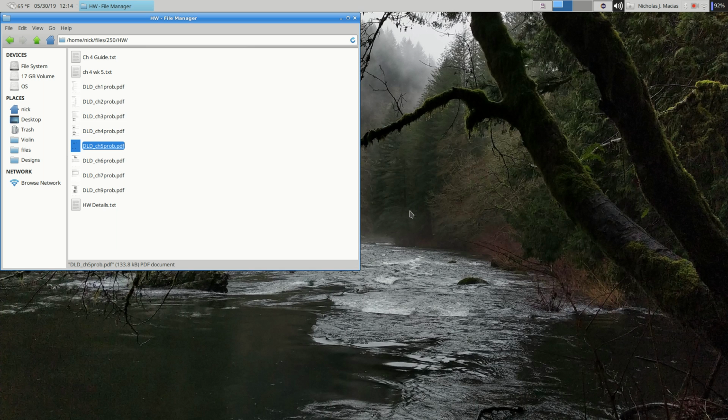And on the homework, if you're moving from state to state correctly and you're not explicitly generating outputs, that's not a big deal for me. So the trickiest part is coming up with the machinery for the flip-flops and how to update the state of the system. And the output's usually just another piece of random logic based on state variables or inputs. So it's just a combinational thing.